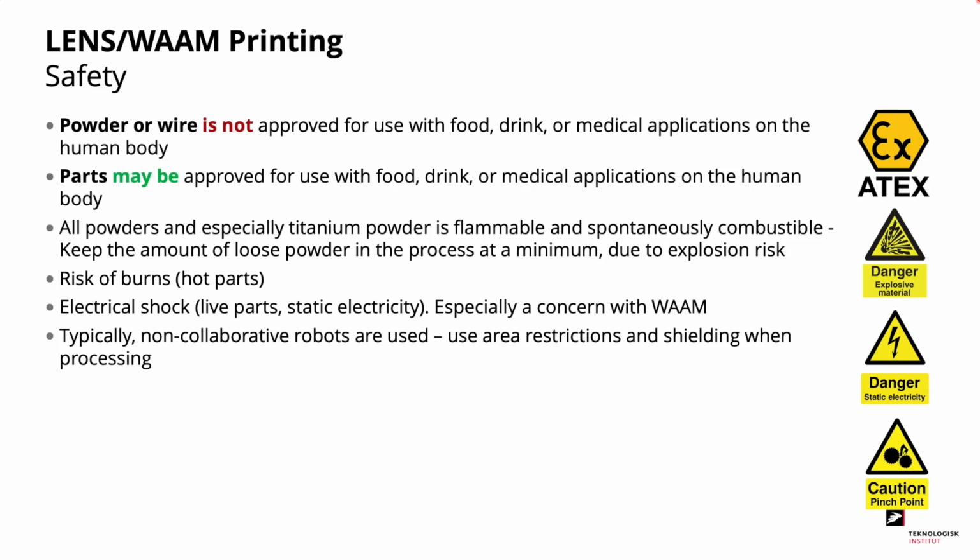All powders, and especially titanium powder, are flammable and spontaneously combustible. You should keep the amount of loose powder in the process at a minimum due to this explosion risk. As you are working with hot parts, there's a risk of burns. The parts are also typically live and there could be a buildup of static electricity. This leads to the risk of electrical shock. This is especially a concern with the WAM process. Typically, non-collaborative robots are being used, so you should use area restrictions and shielding when processing.